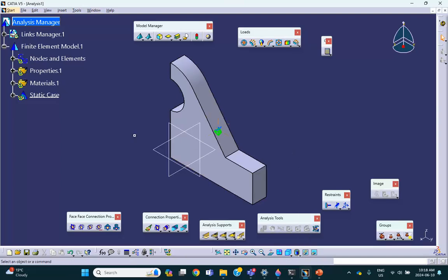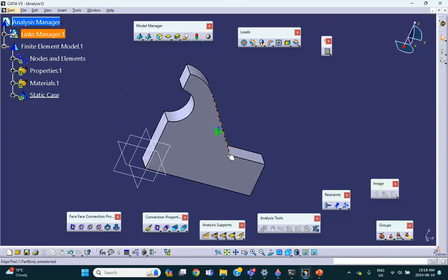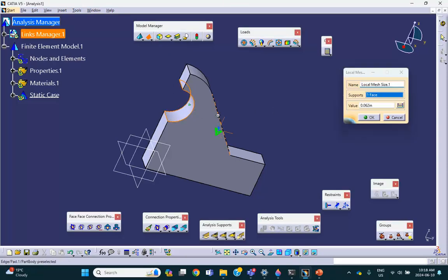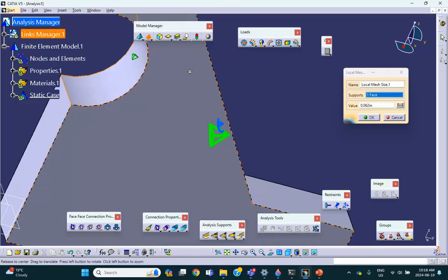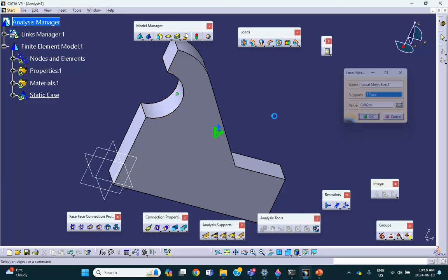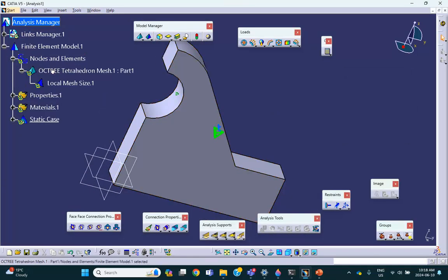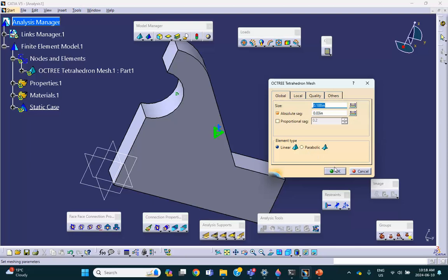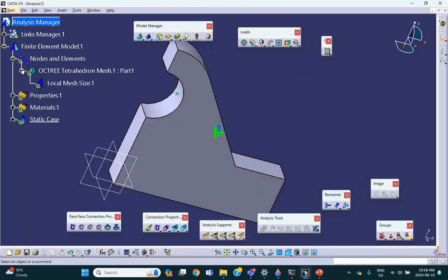All right, the problem says make sure there is a finer mesh around that hole. So let's do that. Remember how to do it. You go to the second icon and there's local mesh size. You select that. And right now it's this, which is fine. You just leave it the way it is. Now, generally speaking, I say default linear and default size.